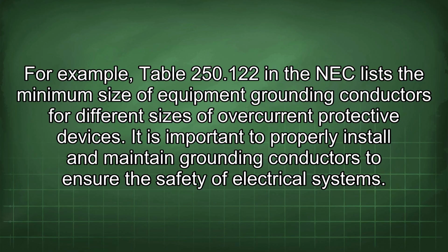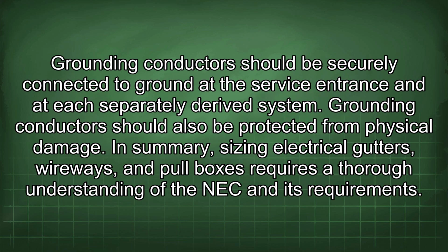It is important to properly install and maintain grounding conductors to ensure the safety of electrical systems. Grounding conductors should be securely connected to ground at the service entrance and at each separately derived system. Grounding conductors should also be protected from physical damage.